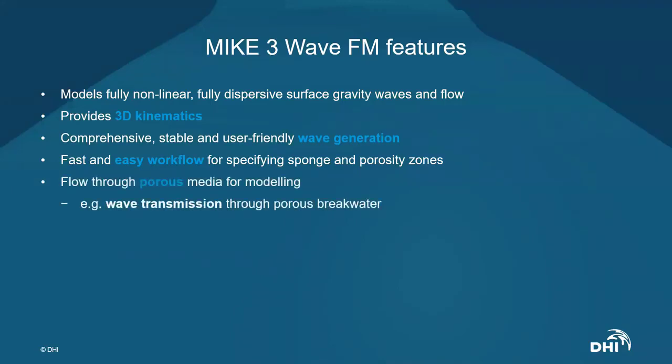We have this comprehensive, stable, and user-friendly wave generation interface where you can easily specify different wave generation zones. You could have multiple wave generation zones, allowing you to easily introduce both sea and swell waves coming from different directions. We also have a fast and easy workflow for specifying sponges, sponge coefficients, and also porosity zones. Sponge coefficients you are interested in doing quickly because you need those to dampen some of the unwanted reflections